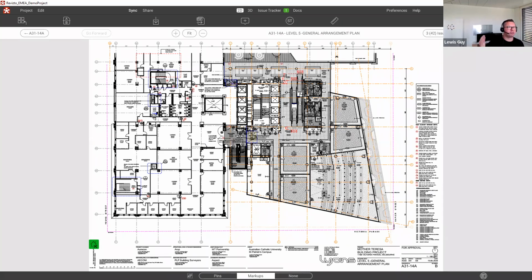So if you're bringing 1,000 drawings in as PDFs, we wouldn't recommend that you do all 1,000 this way. But if of those 1,000 there were 10 key GAs, then it's pretty quick to set up, and it remembers it the next time that you add a PDF to it. So as long as the viewpoint on the sheet hasn't moved, the overlay will still work with the PDFs automatically. So cool. One more before we are done.